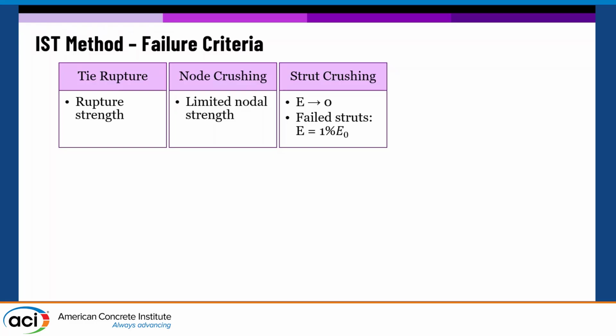Just to be clear to myself, or maybe some people might be interested, what is the conceptual difference between steel-reinforced concrete beams and FRP-reinforced concrete beams with respect to the strut-and-tie model? I think the main difference is that with steel strut-and-tie, you're basically modeling the flow of stresses through the member, and with steel you want the reinforcement to yield before the concrete crushes.